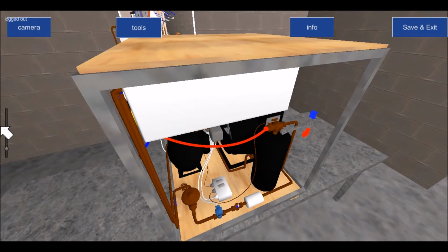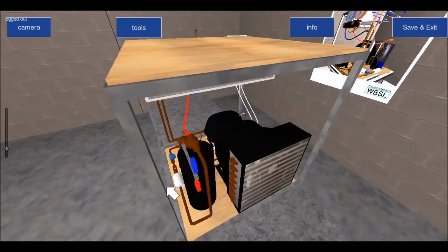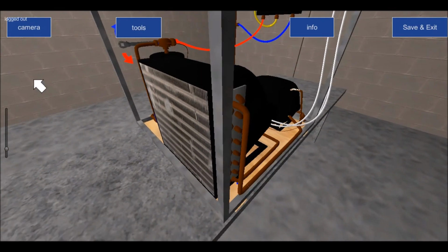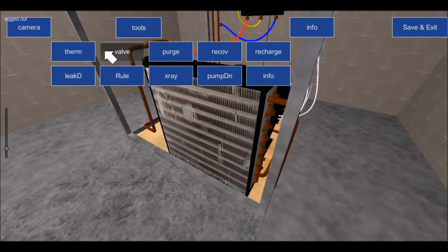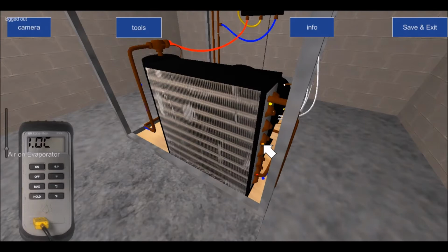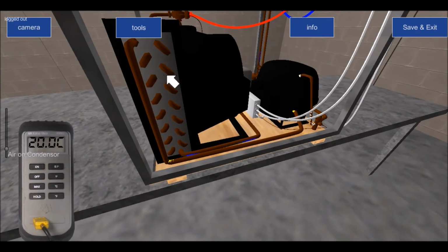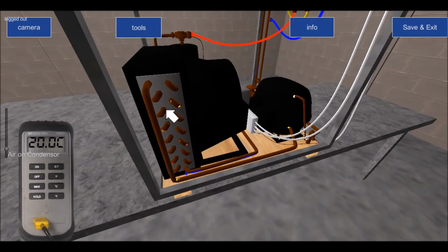So the temperature of the refrigerant inside my condenser will correspond with the pressure that's there. So how do I do that? Well, I get my thermometer and measure the temperature in the middle of my condenser. Remember I said we have a desuperheating zone, a condensing zone, and a subcooling zone, which is down the bottom here, okay?